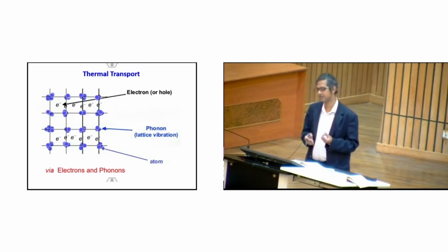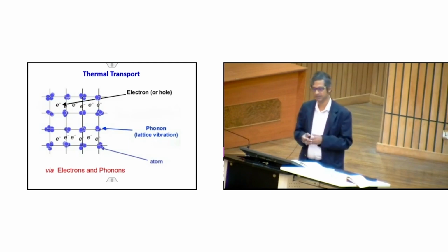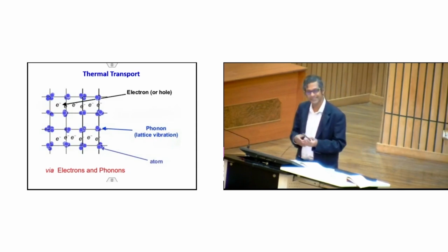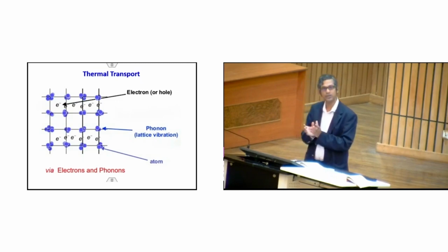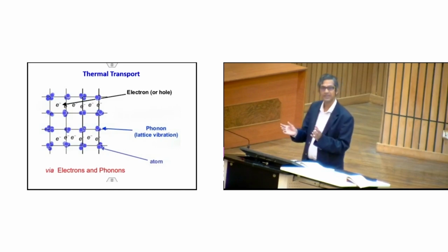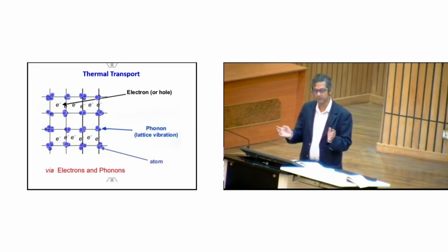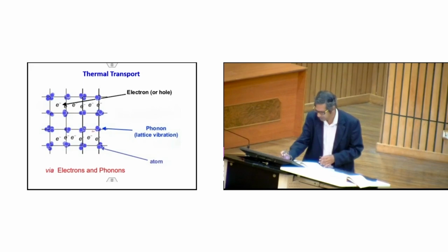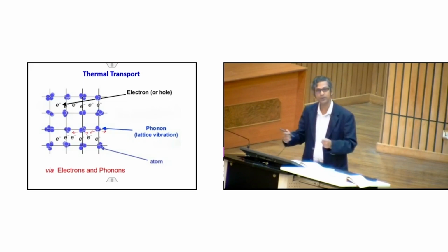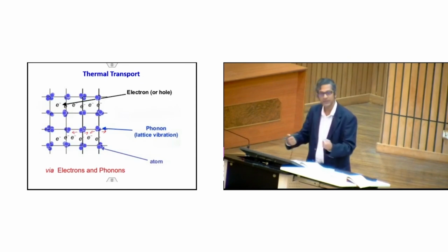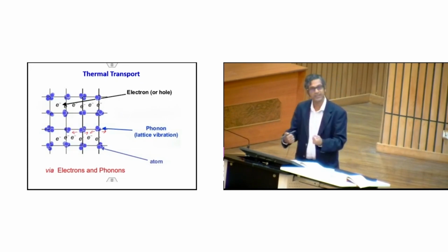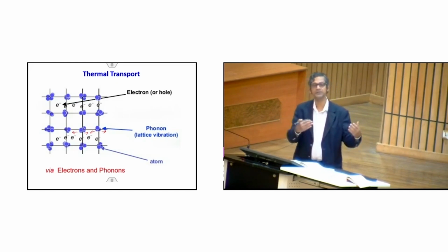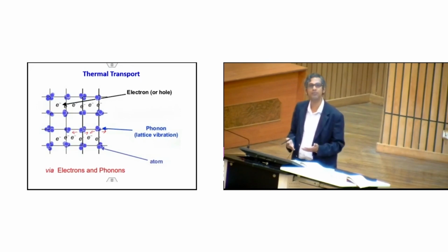That is the important thing. You can also have holes, like in semiconductors, which can also act as a transporting agent for the heat, right. But the other thing which is possible is this: listen carefully to me. As you heat the materials, what would happen? The atoms will also vibrate from the equilibrium positions. As the atoms vibrate, they can get pushed or pulled, and they create a vibration in the material, or vibration in the lattice. So, if this set of atoms is moving like this, they are going to push when they come close, or pull each other when they are going away. By doing that, they act like a simple harmonic oscillator, and a wave will be created inside the material that can propagate and carry the heat, and that is what is known as a phonon or lattice vibration.